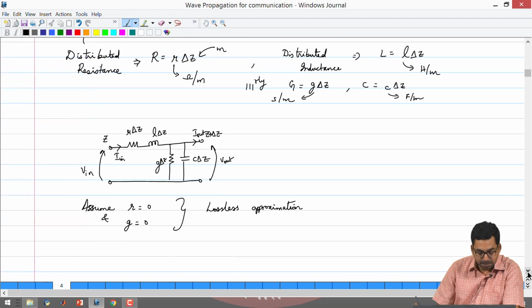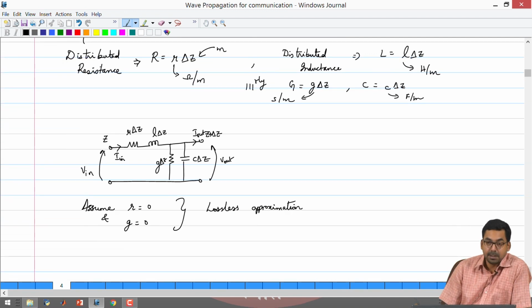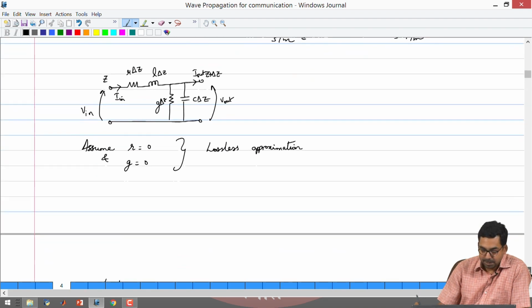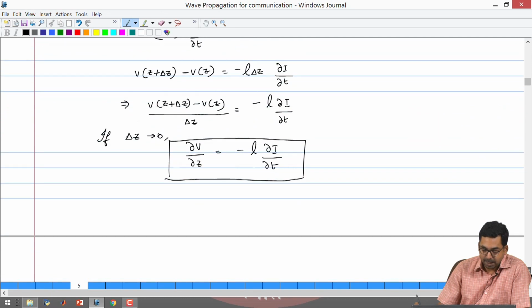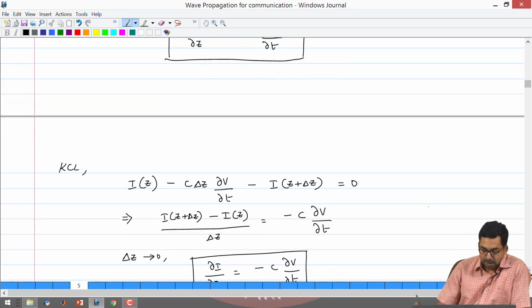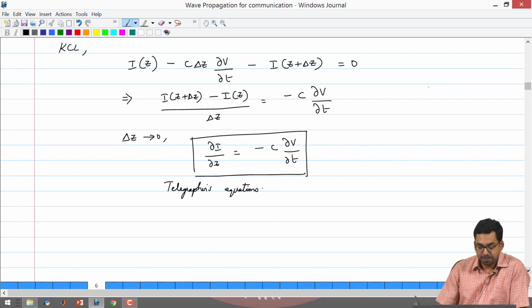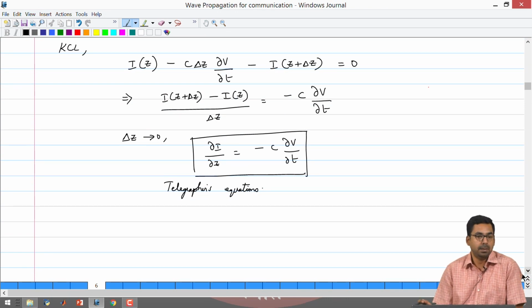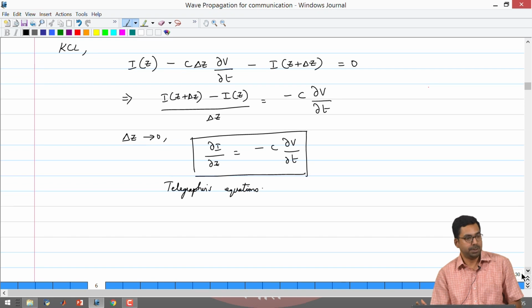We have made a simple assumption that the series resistance and the parallel conductance are going to be 0, alright. This will avoid any potential drops that you will have in these sections of the wire, alright. We are finally modeling a short circuit anyway, so it may be better to start with a lossless approximation. So, we started with resistance and conductance made as 0, and we proceeded to get some constituent equations by using KCL and KVL in one of the sections, and we found that we were obtaining space derivatives in circuit equations. This is where we had stopped, alright.